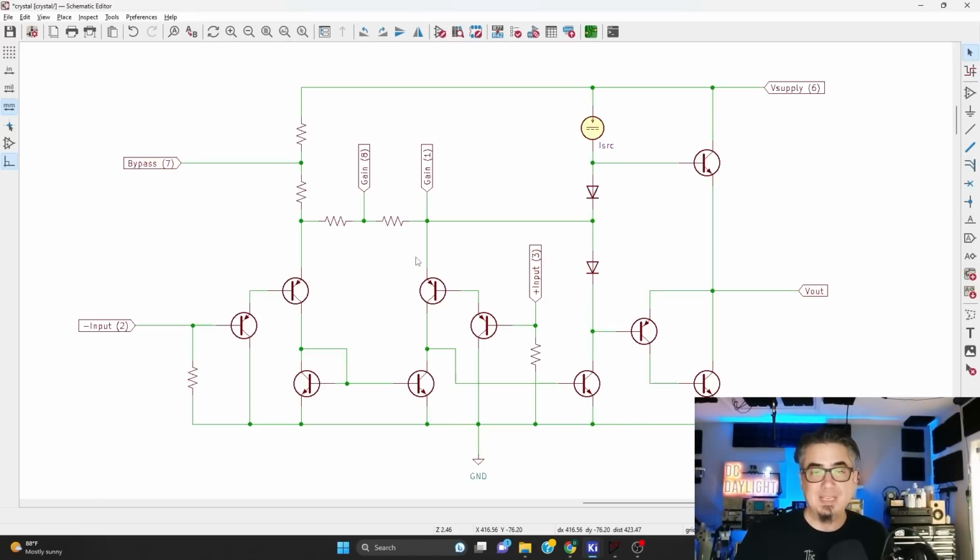And we have a very basic audio amplifier with a fairly decent gain. If we want to increase the gain, there's some things we can do. Let's look at the stages here real quick. So just like a standard op amp, we have some form of a differential input stage. In this case, it's older technology, so we're using BJTs, bipolar junction transistors, most of them PNP here.